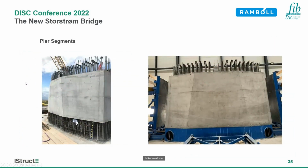This is a pier segment up close. On the right, you see it in the factory, and that blue is the steel shutters. And this, you can just about see in the holes on the left and right the reinforcement poking through, because that's where the steel template is that sets the position of all those bars. On the left, you see the finished article moved out of the fabrication yard, and you can see perimeter bars. You also see at the top the headed bars, and then there's a crane ready to move it.